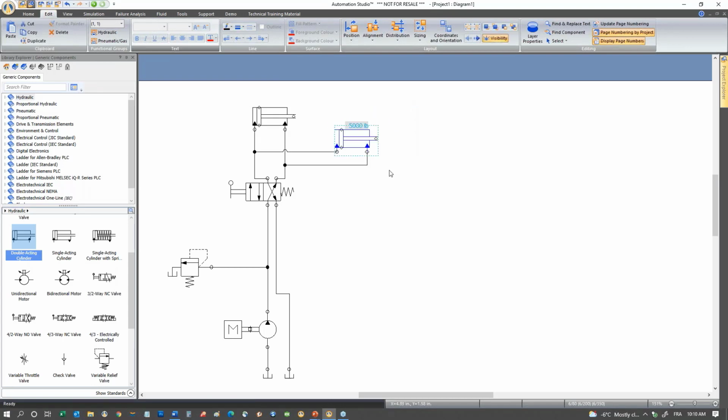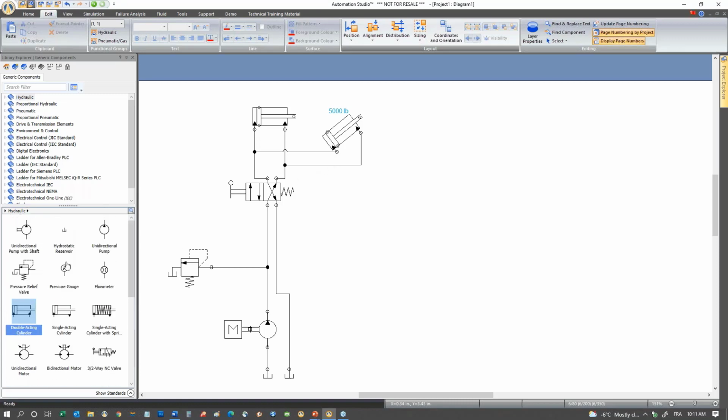Okay. We've put a 40-degree angle in the specification, but we left it flat like that on the schematic because we follow all the ISO standards and we don't turn components on schematics. But for teaching purposes, I can go here, position, rotation, change the rotation point, and actually rotate the cylinder like that. But the purpose of doing that is to also monitor the pressure in the system, what's going to happen. So I'm going to actually drag and drop a pressure gauge over here and a flow meter right at the outlet of the pump.